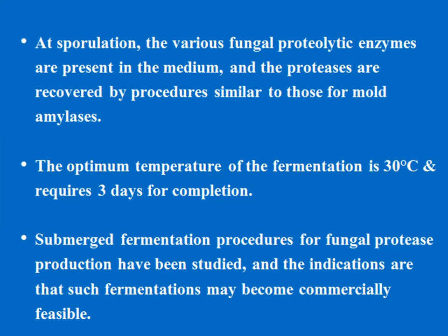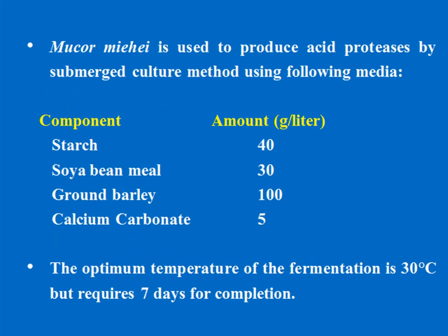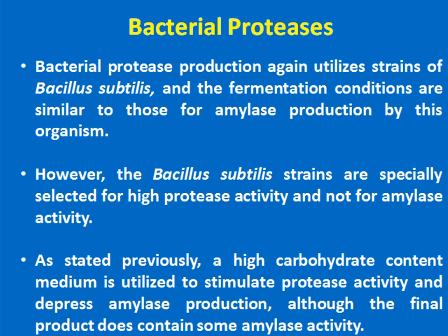Submerged fermentation procedures for fungal protease production have been studied, and the indications are that such fermentations may become commercially feasible. Mucor miehei is used to produce acid protease by submerged culture method using media having components like starch, soybean meal, ground barley, calcium carbonate. The optimum temperature of the fermentation is 30 degrees centigrade but requires 7 days for completion.